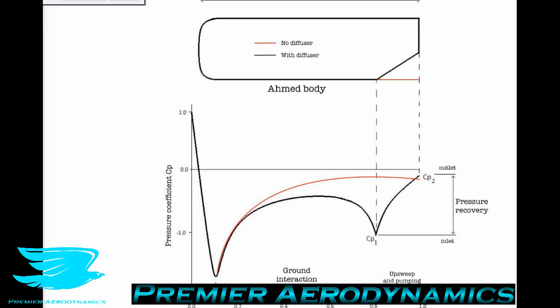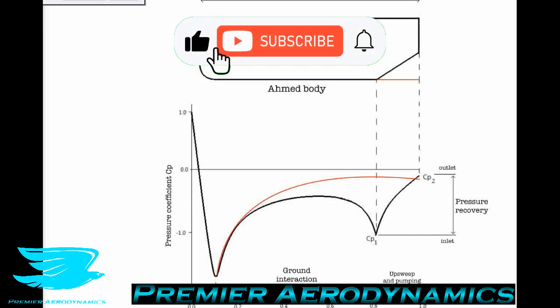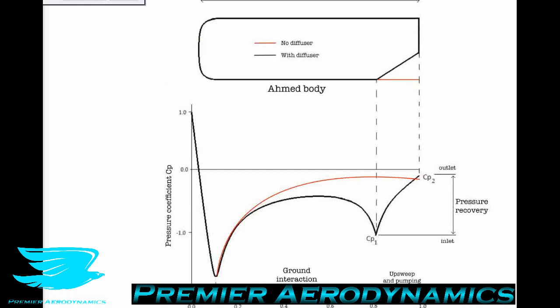even over a very aerodynamic design like an airfoil, because there are always losses, and that means that the flow will always be in a pressure deficit. There is some energy that is missing from the flow, unfortunately, and that is based on how draggy this object is, how efficient or how inefficient it is. But in this particular case, it isn't a huge deal to have even this little loss, because the entire underbody is producing a lot of downforce quite effectively. So, okay, we're getting a drag penalty, but we're getting pretty good downforce. So we're getting quite a good effect here.